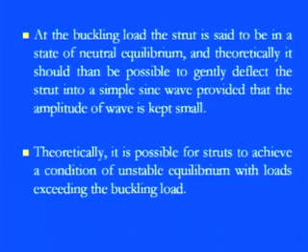So we can say that at the buckling load, when the strut is under the action of buckling, the strut is always in the state of natural equilibrium, because it is now well tuned to nature, and theoretically it should then be possible to gently deflect the strut into a simple sine wave, provided that the amplitude of the wave is kept small.